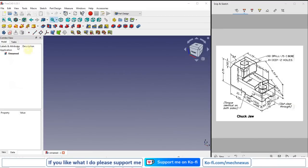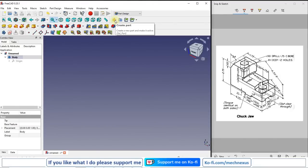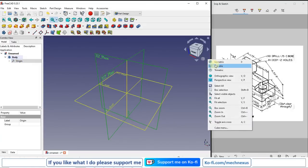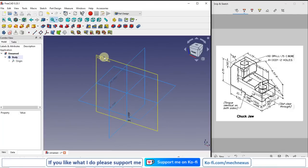So I will create a new body here. Either I can create a part also, but this part works as a container only. So I will press the space bar and on my plane. Now as per our plane orientations, we will draw our base sketch on the XZ plane.